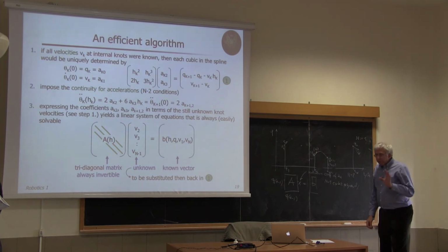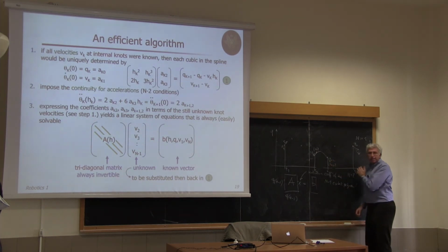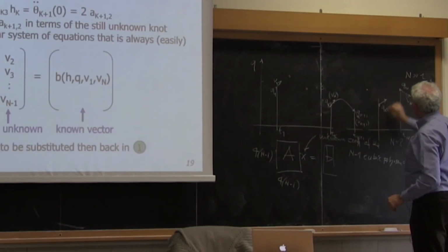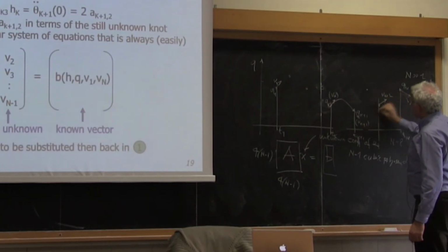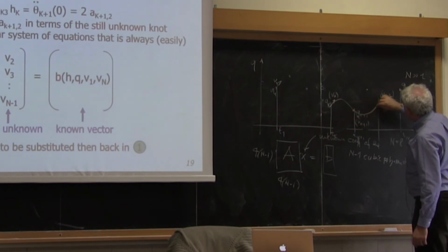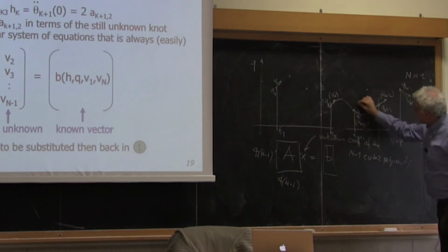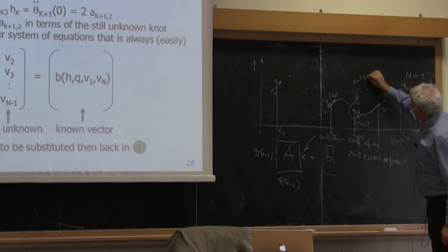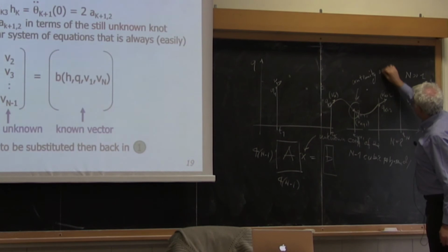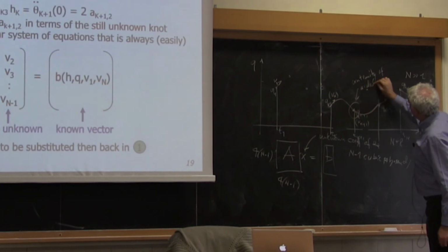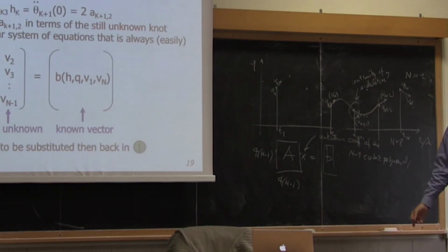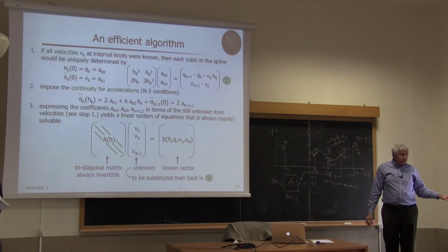But pay attention, if you do this and you specify velocity like this, and then you specify, let's say, the following Qk plus 2, and you're specifying a velocity Vk plus 2, so you locally have another cubic like this, but here there's a problem. You don't know if you have continuity of acceleration. In general, you will not.